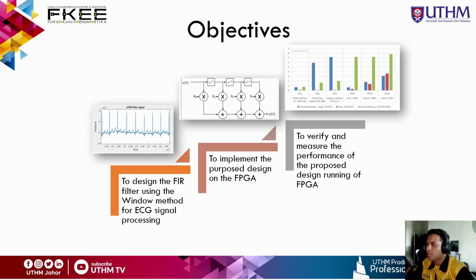Okay, next, the objective. For the first one, to design the FIR filter using the window method for ECG signal processing. For the second one, to implement the proposed design on the FPGA. Last but not least, to verify and measure the performance of the proposed design running on the FPGA. For the PSM1, I just go through objective number 1, which is to design the FIR filter using the window method in MATLAB. After that, I will show you how to filter the ECG noise from the original signal using the FIR filter in MATLAB.